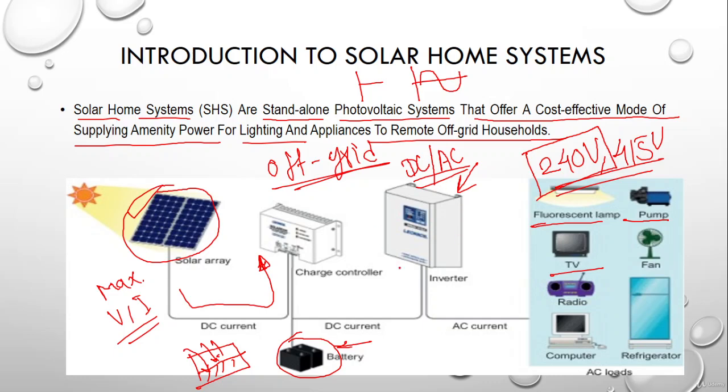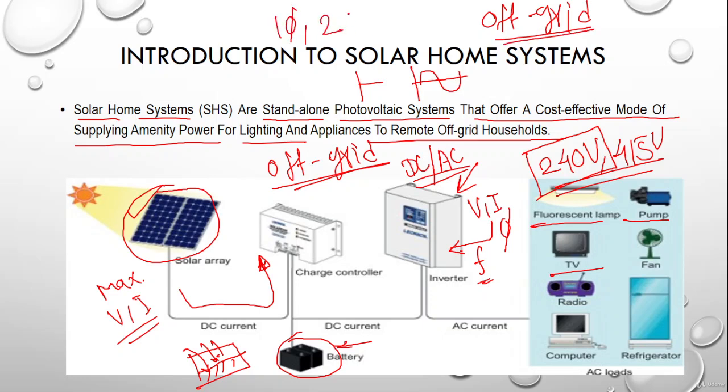In some cases, if we are using grid supply, that is a hybrid kind of system, when discussing the solar home system, the role of the inverter is also to synchronize the voltage, current, phase and frequency coming from the utility supplier. But in the smaller off-grid home system, an algorithm is already fitted so that it gives the power in a single-phase manner. It gives an adjustable voltage up to 240 volts, and the typical amount of current as per the capacity of the solar power plant.